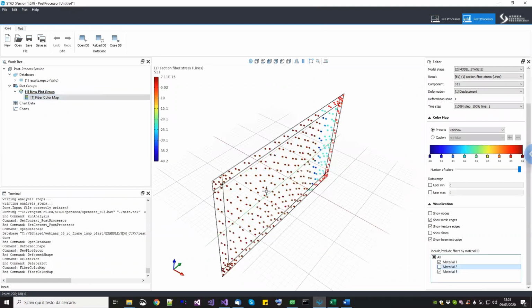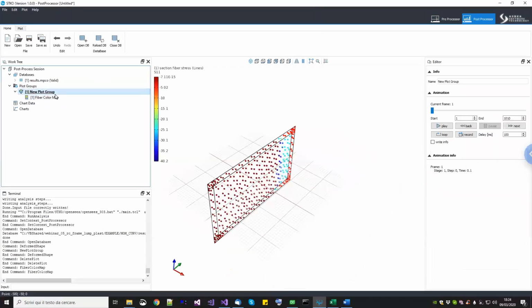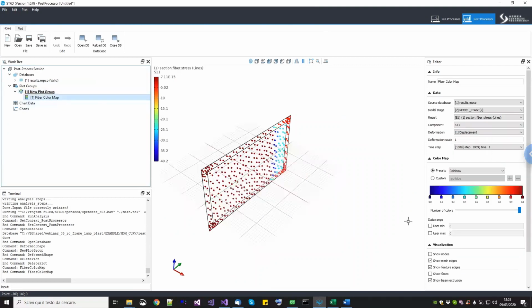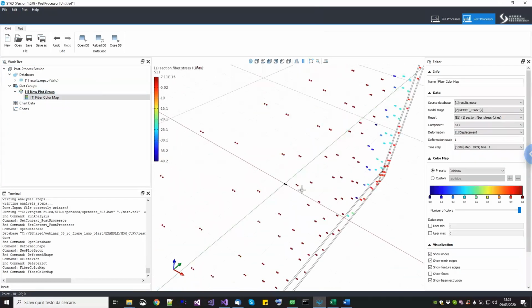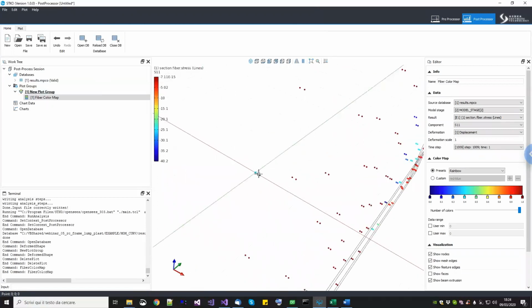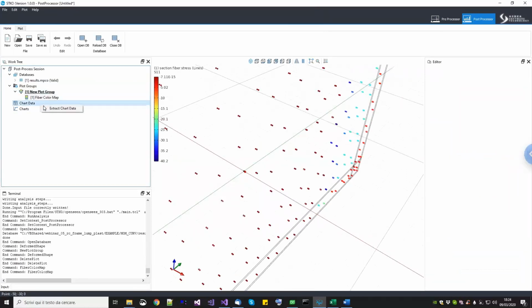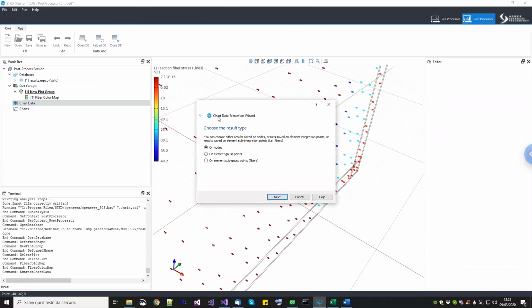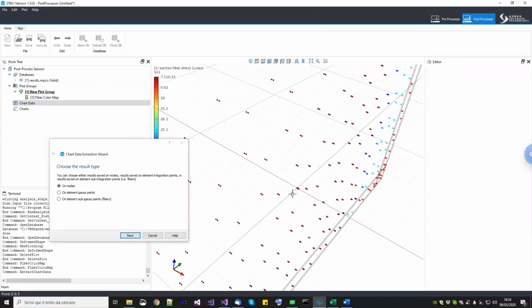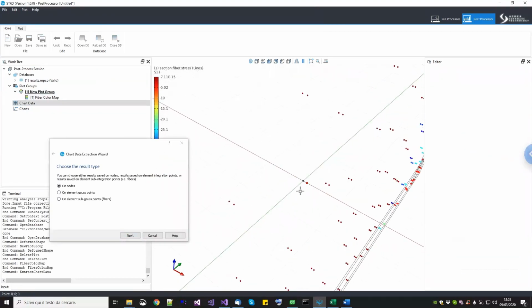in the beam. Let's switch off the steel rebar so we can see the stresses. So this is what we expect, of course. Now let me switch off the nodes so that we can select the top node, these two. So this one will be the end node, because from this node we will extract the moment curvature response. Now, as I said, since I applied a rotation on this node, at the same node I have the reaction force, which is actually equal to the applied moment.